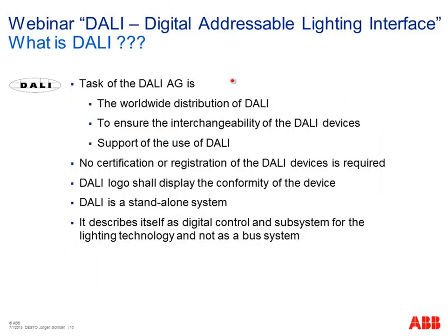This working group DALI, what is the task of the working group? Of course, the worldwide distribution of DALI is a target. And though it started years ago here in Germany and Europe, we can really say right now it's an international system, and in many countries DALI is known and used. More and more countries create solutions together with DALI. So it's a real success story, but of course there's always something to do to promote the system. Another big topic, compatibility, interchangeability, as already mentioned. It has to work, of course, because everybody expects this and would like to choose different DALI devices which can work together.